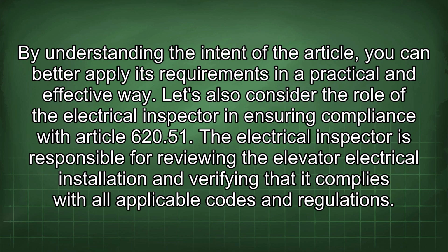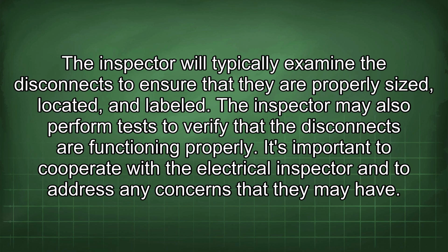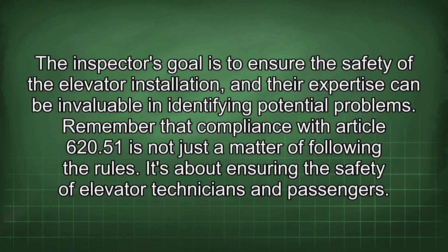Let's also consider the role of the electrical inspector in ensuring compliance with Article 620.51. The electrical inspector is responsible for reviewing the elevator electrical installation and verifying that it complies with all applicable codes and regulations. The inspector will typically examine the disconnects to ensure that they are properly sized, located, and labeled. The inspector may also perform tests to verify that the disconnects are functioning properly. It's important to cooperate with the electrical inspector and to address any concerns that they may have. The inspector's goal is to ensure the safety of the elevator installation, and their expertise can be invaluable in identifying potential problems.